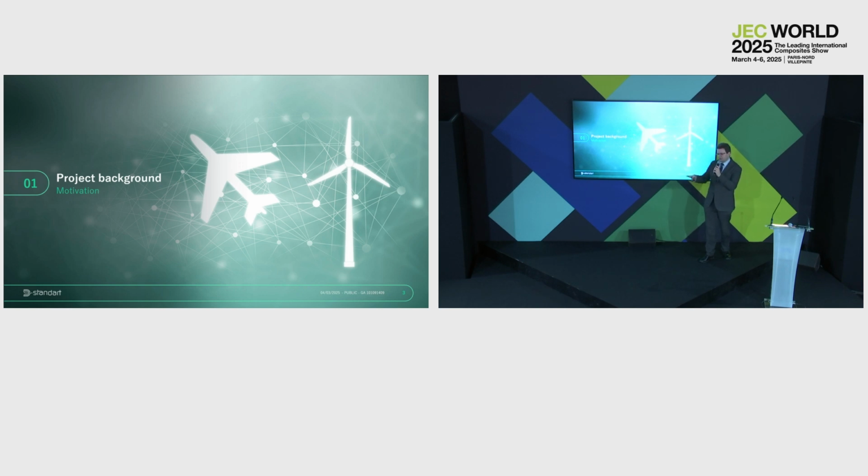We're at JEC, so I don't have to explain to you all the advantages of composite materials. And what probably most of you already know is that the first generation of composite materials, analysis, failure analysis was not so easy. Getting really consistent material quality was not so easy. And so we compensated by increasing safety factors, by having knockdown factors, quite generous margins in our structure. But over the past decades, we've become better at analysis. We've become better at quality control. So now we would like to make better use of our materials to bring down those margins and use our structures more efficiently. But that means we now have to worry about a new issue, which is fatigue.